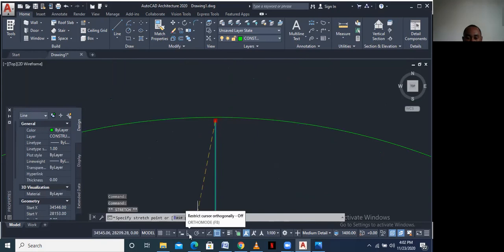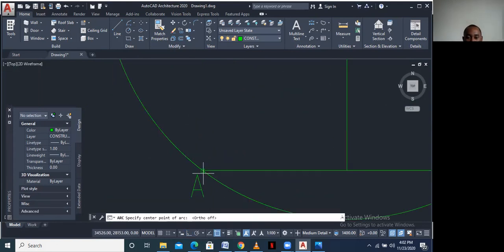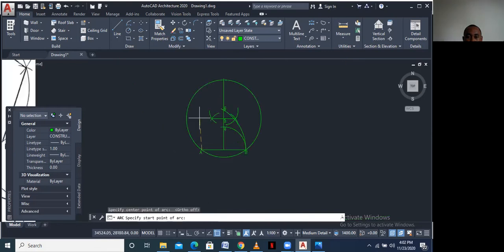So let's just turn on the auto mode to make sure it's a vertical line. Then I select arc, turn off my auto mode, open my arc to this direction, and I use 40 as my radius because it should be the same length as AB. Remember, the regular pentagon has all sides equal.